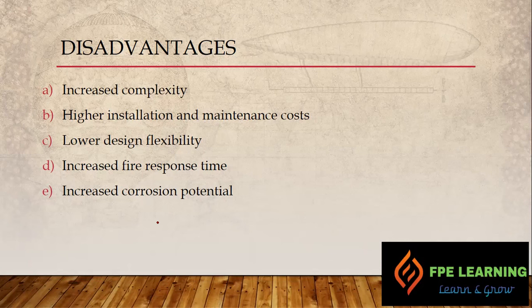Because I discussed that when water and oxygen meet, it will damage the internal piping and it will corrode very fast. So this is why a dry pipe system needs more maintenance and higher knowledge to design. We want to make sure that our dry pipe system is designed in such a way that all the water discharges after the activation or after a maintenance issue. If there is water inside, it will cause corrosion and decrease the efficiency of the system, and it may become obsolete maybe after 5 years, because corrosion is very tough on those metals. We have to be careful regarding that. Moisture plus oxygen increases internal pipe corrosion.